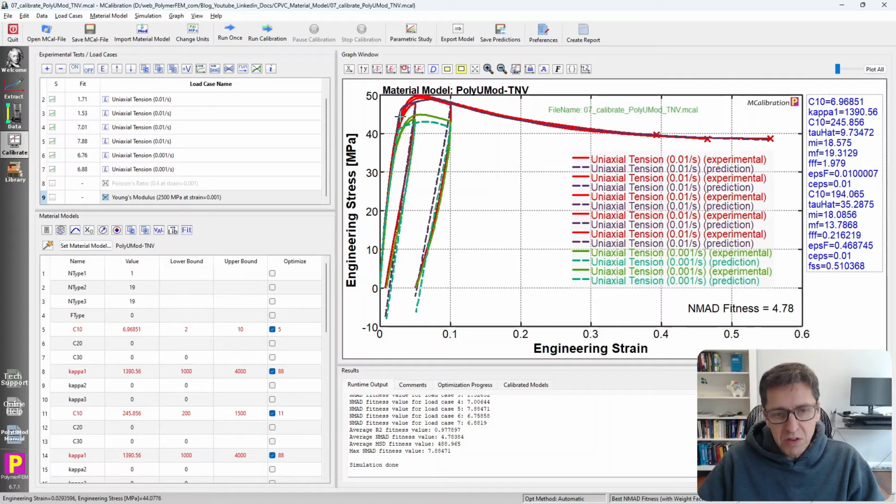The way this works is that it captures the rate effects, the softening, and the unloading pretty well. It overestimates a little bit of the permanent set in this case, but it's a pretty decent representation of the experimental data. And this is something that I would be okay using. It looks pretty good to me. I should point out one thing about this model compared to the winner model. In this model, the softening that occurs during unloading is represented using sort of a damage approach.